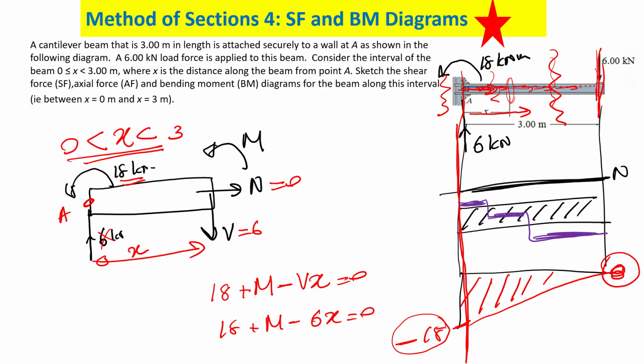You can find out only this section undergoes this much shear force. This section is less, this one is higher. So likewise you can select the section size without wasting your material. If you know the internal forces, you can wisely choose the material and the section thicknesses, because the same force is not acting everywhere, isn't it? So you don't need to waste.